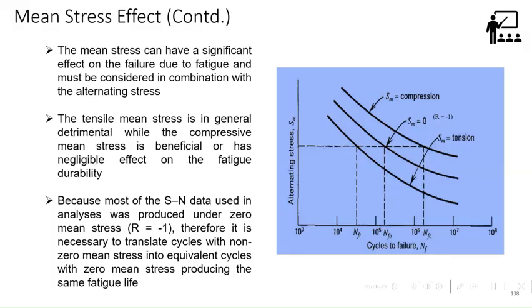And you want to know what the SN curve is for R equal to 0.25, you can do the interpolation. But if R is equal to 0.6, you cannot extrapolate. Okay, that is a general standard practice. It's not recommended to extrapolate beyond the range of experimental data which has been tested.